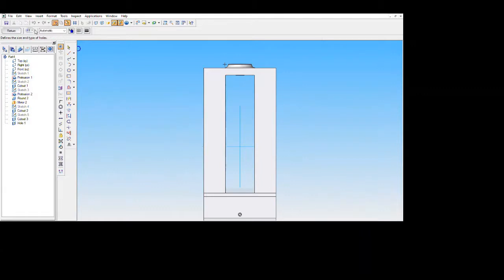and click on the hole properties. It should be countersink. The diameter is 3 and the countersink diameter is 5, and it is through next. Click OK. Place it here, and the distance from this to this circle is 10.